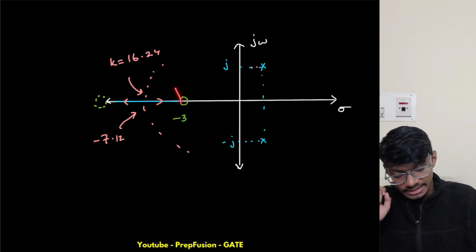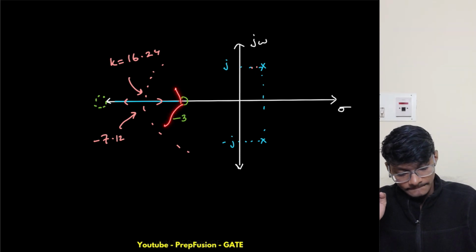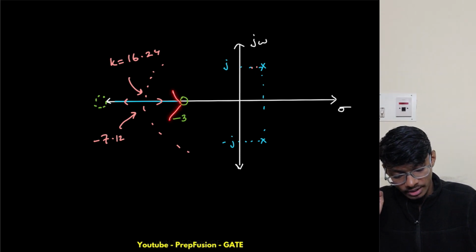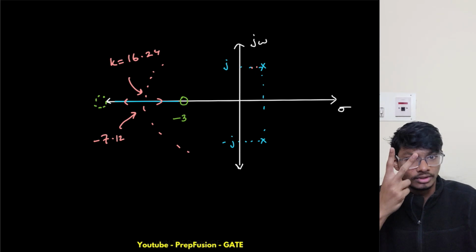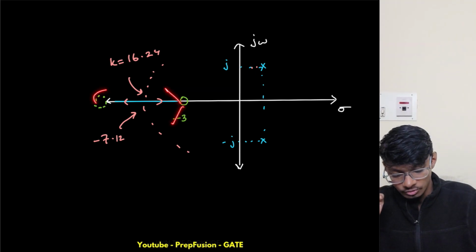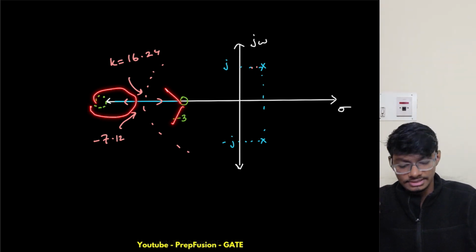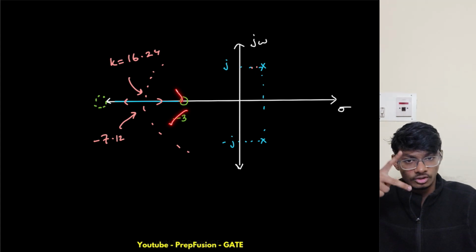If it goes in this axis, I will need another branch to go in this axis. Then I will have two branches here, but still I need another branch which will terminate at this zero. But I already used my two branches here, then who will provide the branch here? Hence that's why we eliminate that case, they can't go in the complex axis.